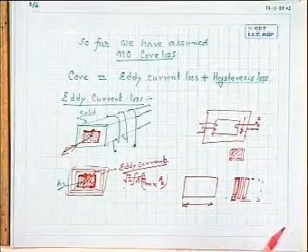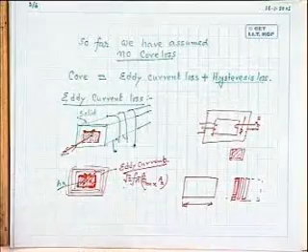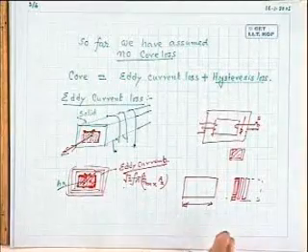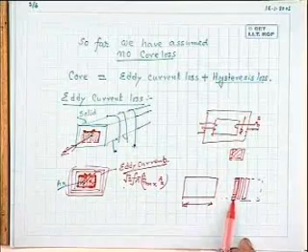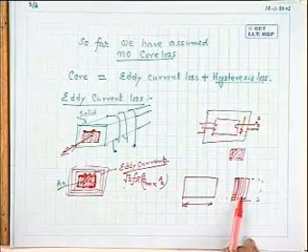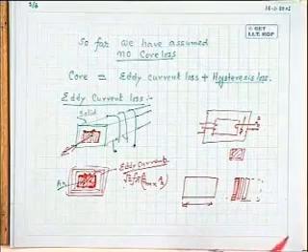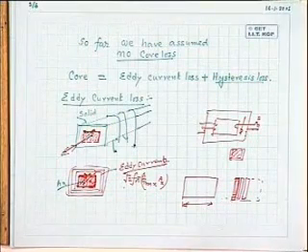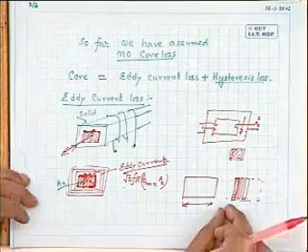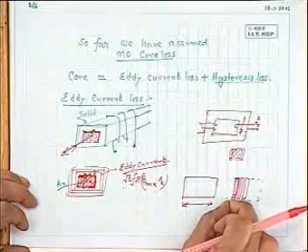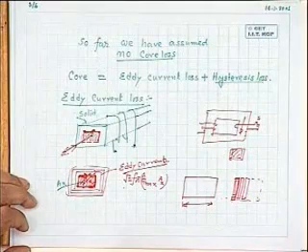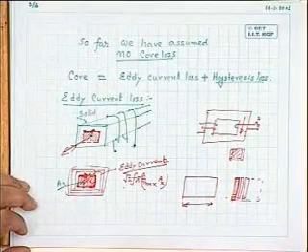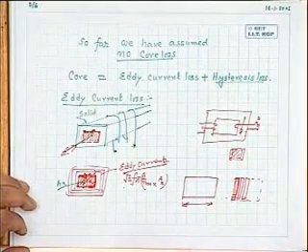And this one I am getting, not doing any mathematics, just by using my common sense. The solid block of iron will have a lot of eddy current losses, understood. Now, this can perhaps be reduced if I use thinner plates. Why? Because the path of the eddy current flow will be small. In fact, if you imagine this is brought down to a very low thickness, eddy current will practically not exist.